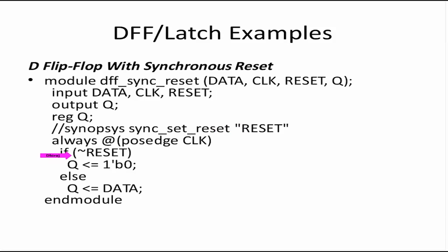Even if you don't use it, the hardware generated will be correct. This is used in very special cases. I'll come to it in the next lecture. But here again, if your library contains a flip flop, a sequential element with synchronous reset, then it will use it. But if not, the functionality of reset can actually be implemented using combinational logic.